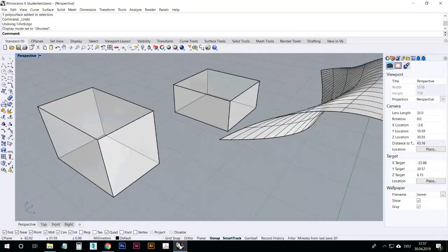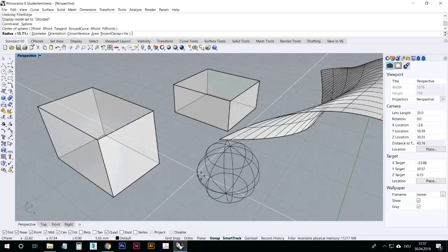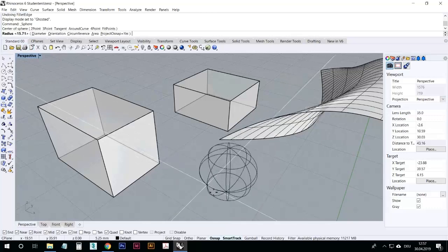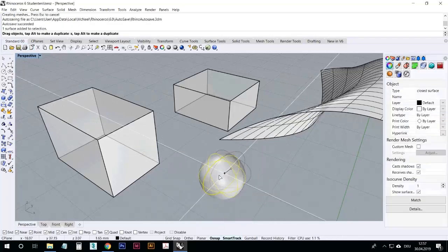We can walk over to the solid tools, it's called solid creation, of course, I'm sorry. So here, box corner, we already tried that a couple of times. We have a cylinder as well. We have also spheres. Works exactly like the circle, more or less, center of sphere, and then I press somewhere and then let's pull, or type in a specific radius, and then I can make a sphere, like that.